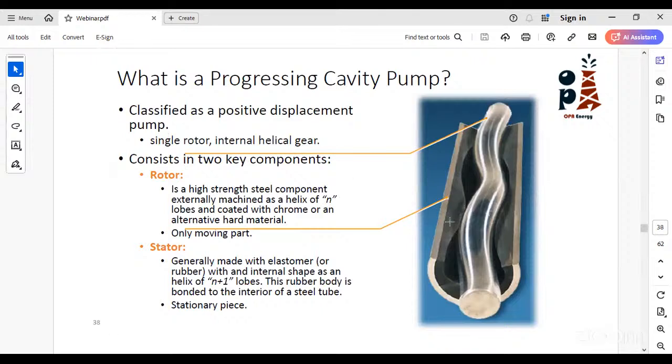This black dark thing is the elastomer. You can differentiate between the stator body itself and this elastomer, that is the dark thing that is bonded very strongly to the stator itself. And this material is mainly based on rubber or different kinds of polymers, for different kinds of applications that can withstand different temperatures and different components or composition of the fluids that you are producing.